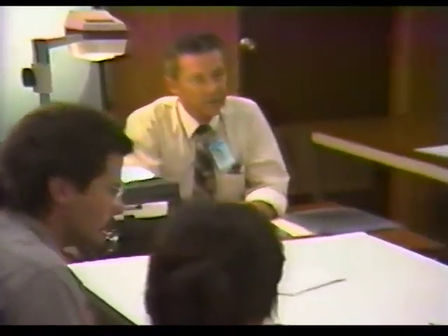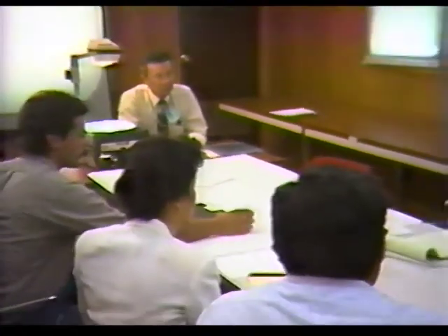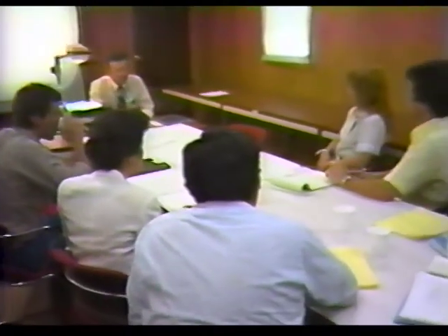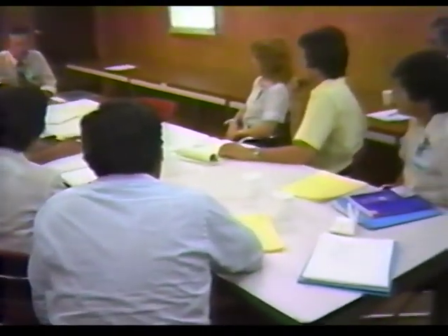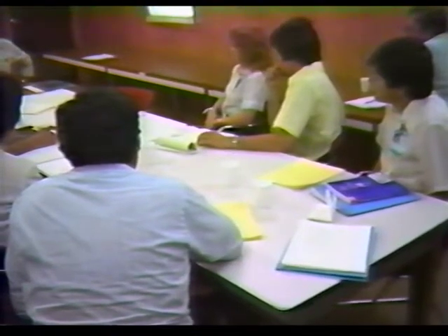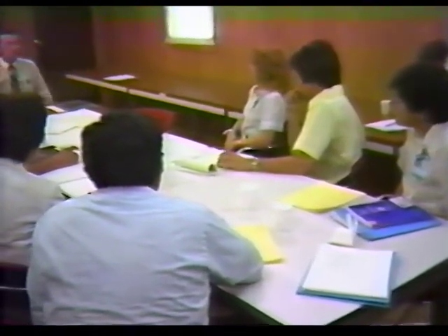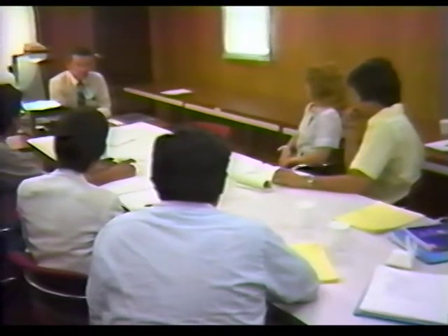In unhardened oxides, it's all over the map, depending on what they've got in that oxide. It can go on for hours, really. And in some of it, it takes minutes to even get more than half out of it. So it jumps around a lot. If you have an elevated temperature, would that go faster? It goes faster at an elevated temperature. But when you're talking about time scales of a millisecond or less, you usually can't see much difference in the annealing characteristics.